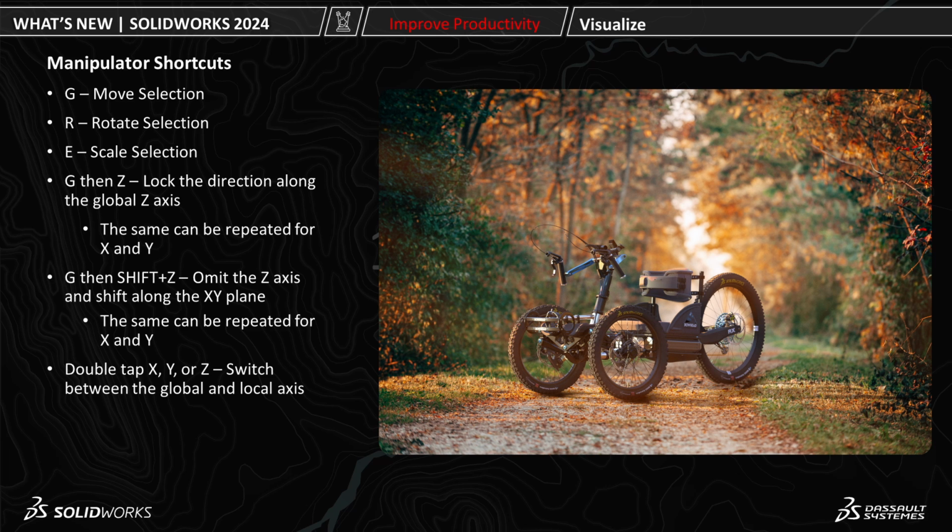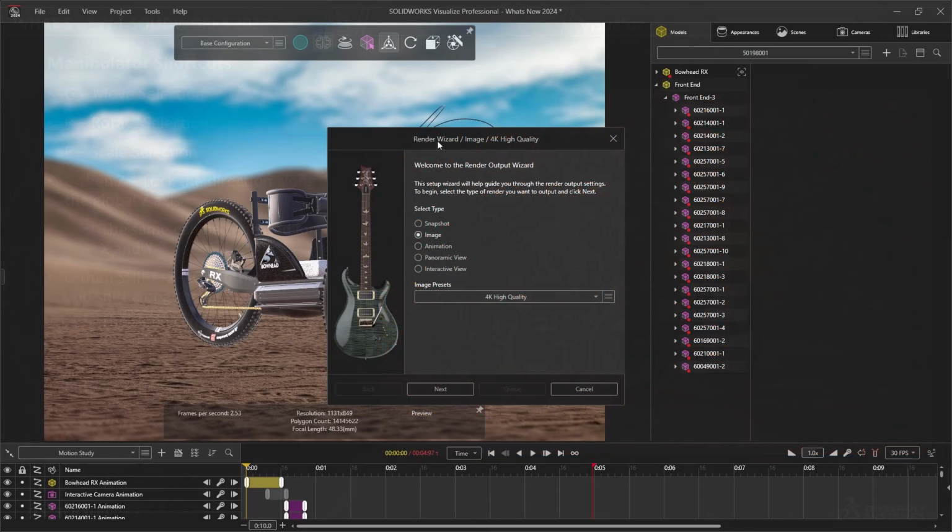You can utilize G for move selection, R for rotate selection, and E for scale selection. You can even combine these commands such as G then Z will lock the direction for movement along the global Z-axis. G then Shift plus Z will omit the Z-axis and move along the XY plane. And adding even more flexibility, you can double tap X, Y, and Z to switch between the global or local axis. The output wizard has also gotten a facelift in 2024.